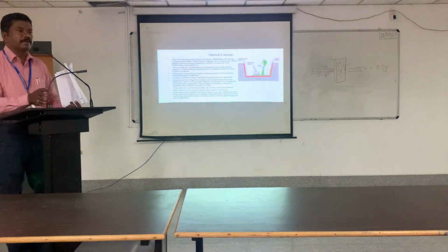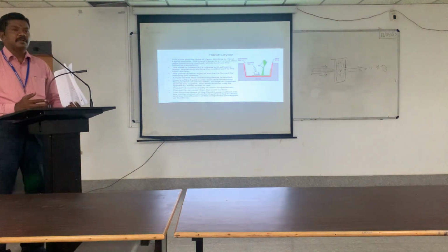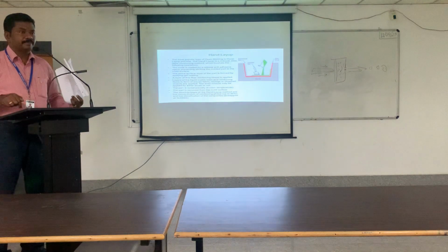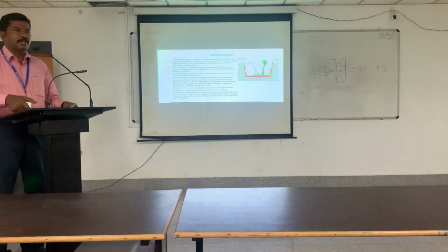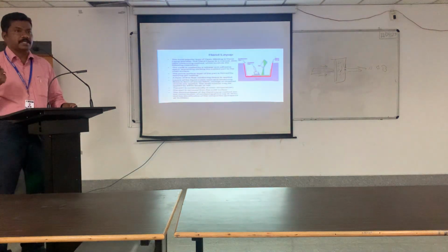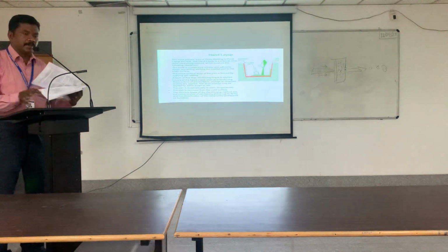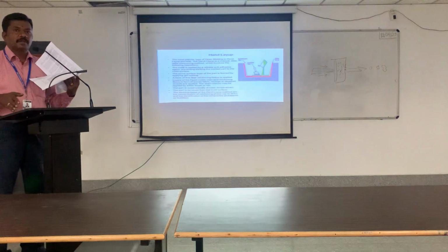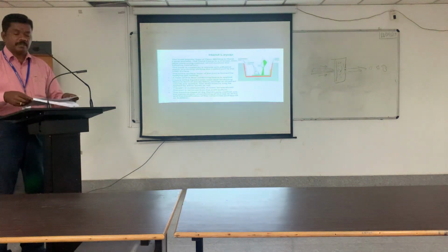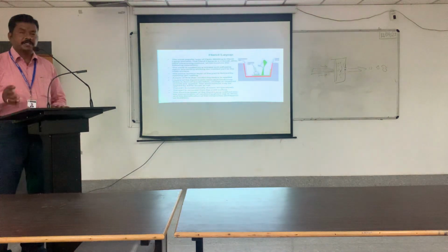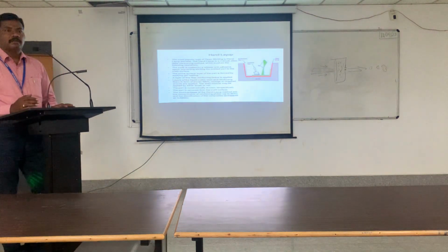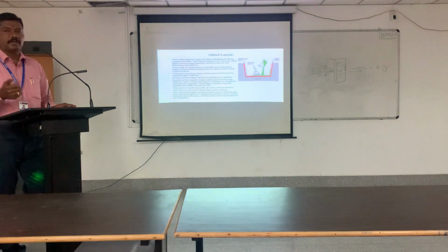Mostly they will apply wax, or in normal laboratory work they will use a simple OHP sheet. They will put an OHP sheet, and upon curing, the sheet will be taken off very easily. Either you can apply the wax using a brush, then stack the required amount of reinforcement and matrix material for the required thickness, and then finally take it out.